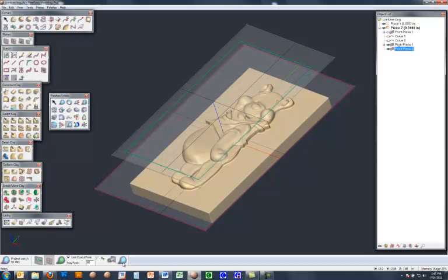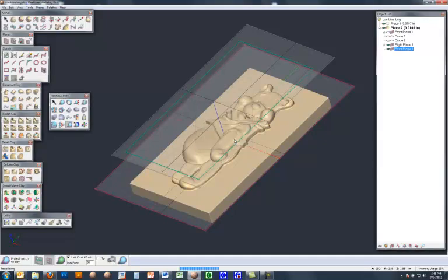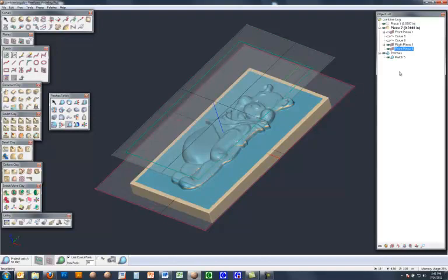FreeForm goes away and calculates the patches. This little dialog box pops up, which is giving me the edge fitting statistics from neighbouring patches. For now, you can pretty much just ignore this and hit OK. And then FreeForm tessellates the surfaces which it's just created.